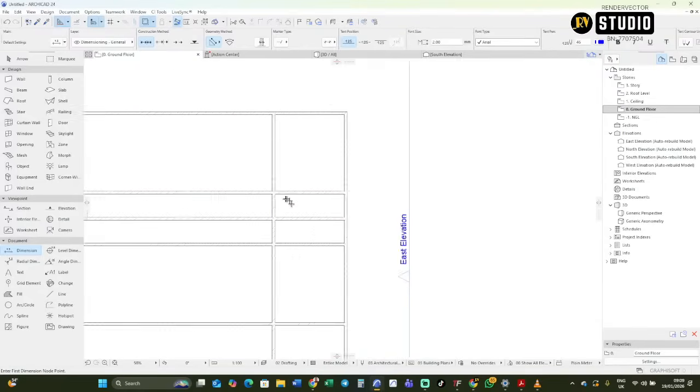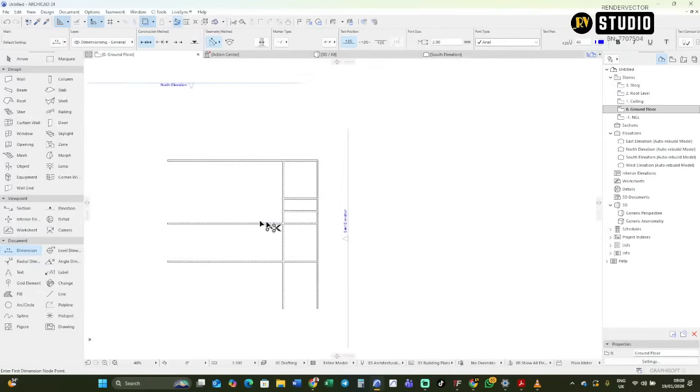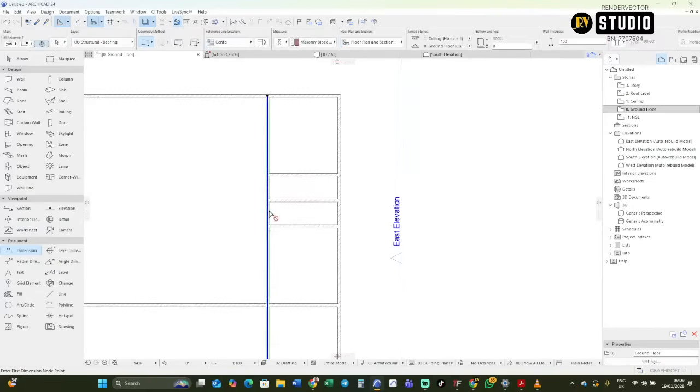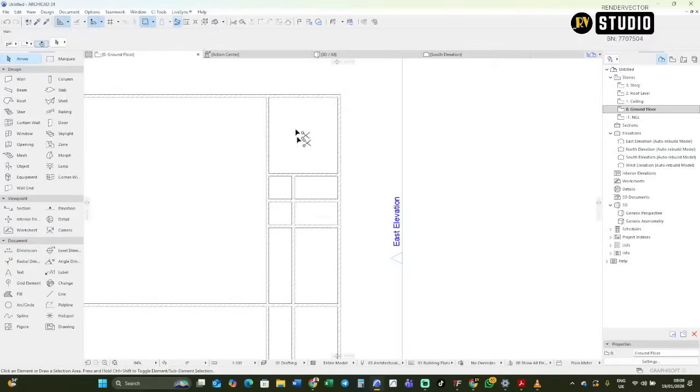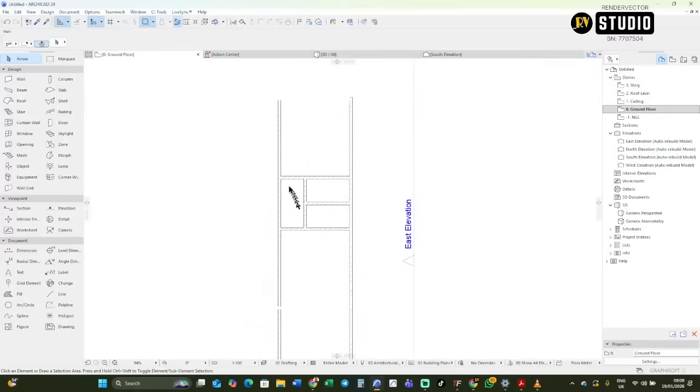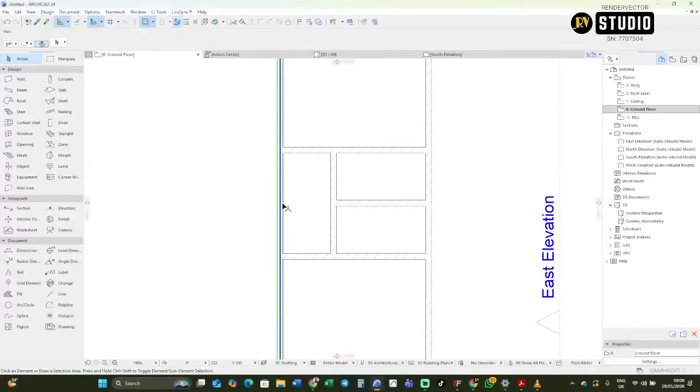So now let's cut all these things out. First, bring in this Control Shift D. I'm going to give it 1200 for a lobby. So 1350. So it's going to actually be 1200. Then I'll hold down my control and cut this, cut this, cut this while holding down control, cut this. So there's going to be a door here, and then there's going to be a lobby here.